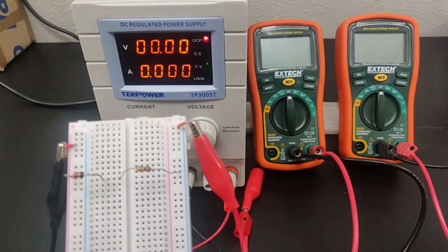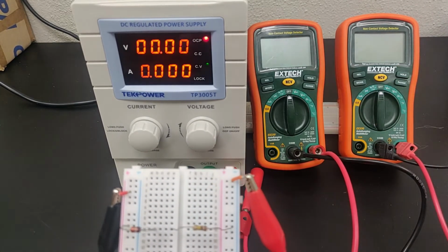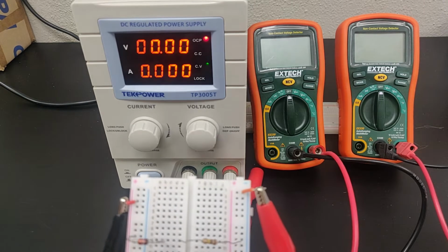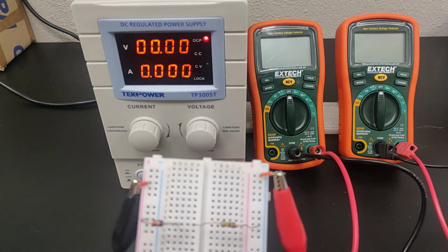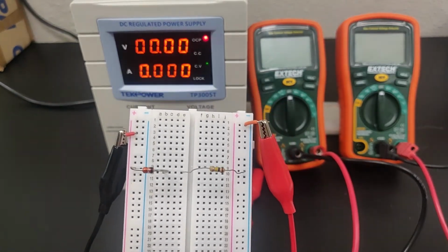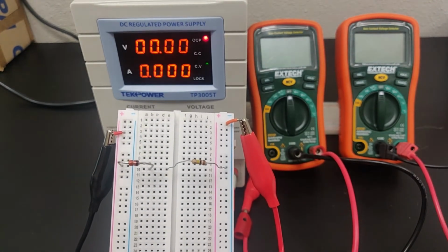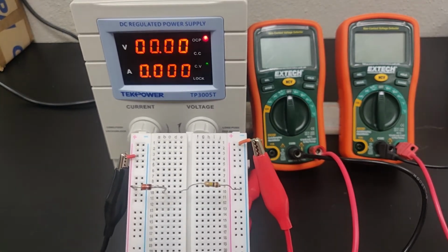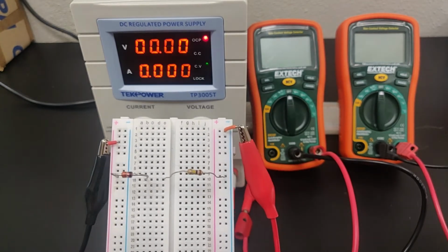But the reverse bias, if you plotted out your data, or actually just looking at what we just measured for the signal diode, you saw that we had a voltage drop of up to like 30 volts, and there was no breakdown. And we didn't want to reach that breakdown because if we did, the diode would be ruined. It's an irreversible process once it breaks down. The Zener diodes, by contrast, are designed to break down. It is a reverse process. So we're going to be making similar measurements for our Zener diode and finding where that breakdown point is and what it looks like.